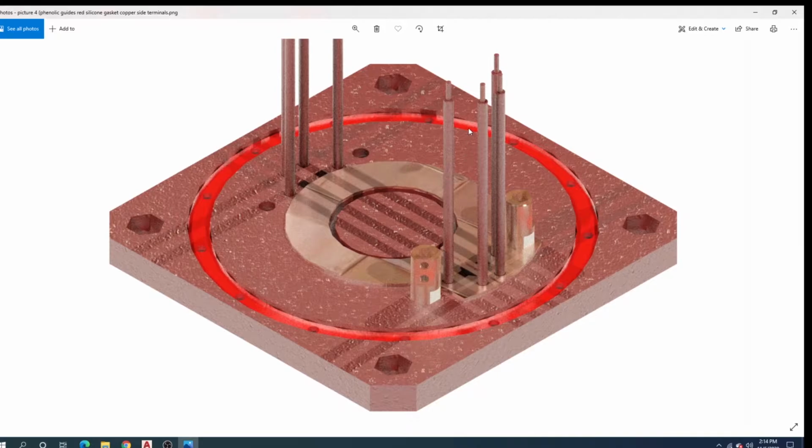These parts here are stages of what I call coil layer guides. Obviously you see that they're guides. As you are assembling this thing, these help maintain precise coil layer location, so everything will match up and stack up correctly.